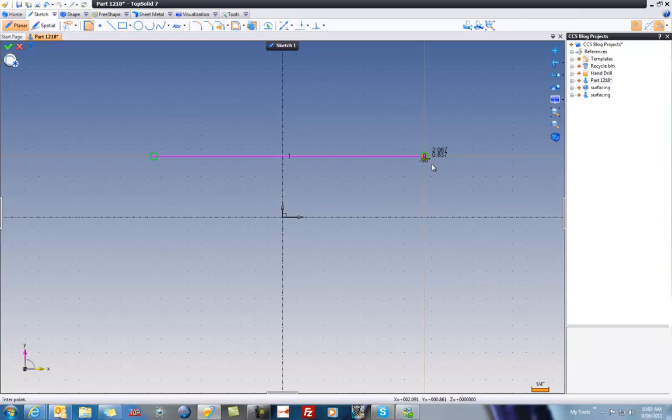And I want to take this sketch and go ahead and just make a little arc there. Why not to there? Make another arc. Perfect. Now, first thing I want to do is I want to locate the center of this arc right on that axis. And just like that, by dragging it, the software automatically applied a coincident relationship there.